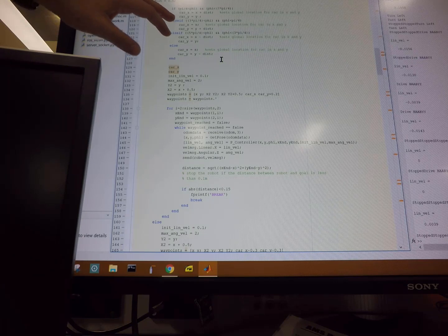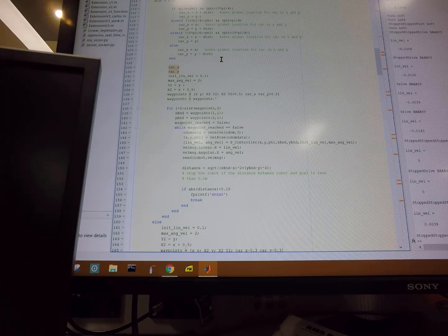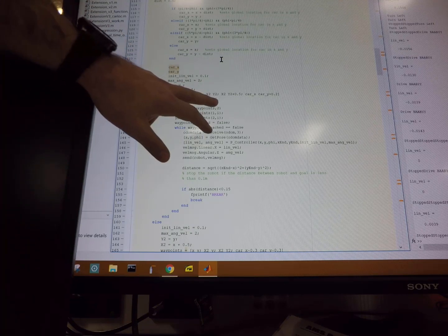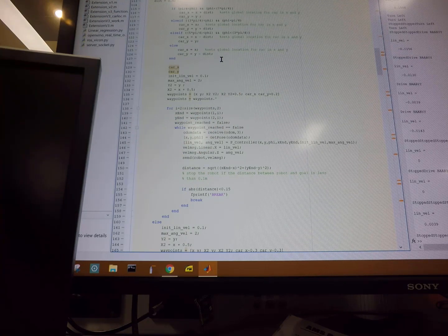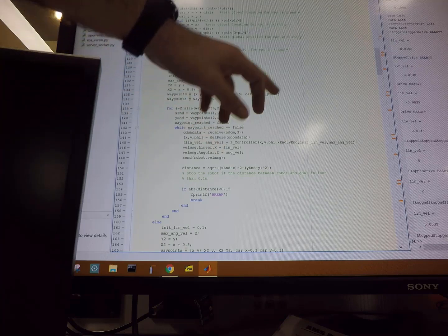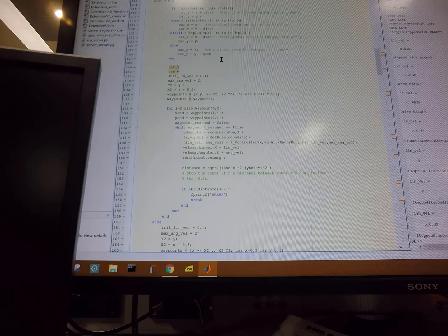And then we've just worked out a rough distance using that measuring board at the back there, worked out how far the car is versus how many pixels we can see, and then that is just a linear speed controller between that. Then from the waypoints, it will actually dynamically set this X2 and Y2. If we say the bottle is a couple mil big, we put a bit of an inflation distance on that, just so it'll make sure it gets around it. And then it'll pick up the last car location, and that being the last waypoint it should drive to. So pretty dynamic in the sense that the car can be anywhere within the Vicon. We can run the test in any angle, any direction, and it should, in theory, with a bit of buffering, work.